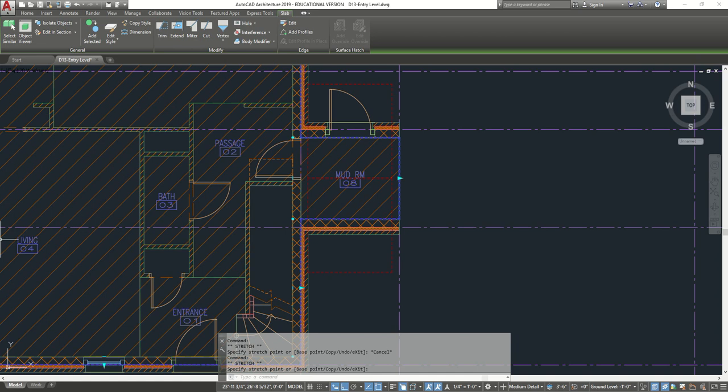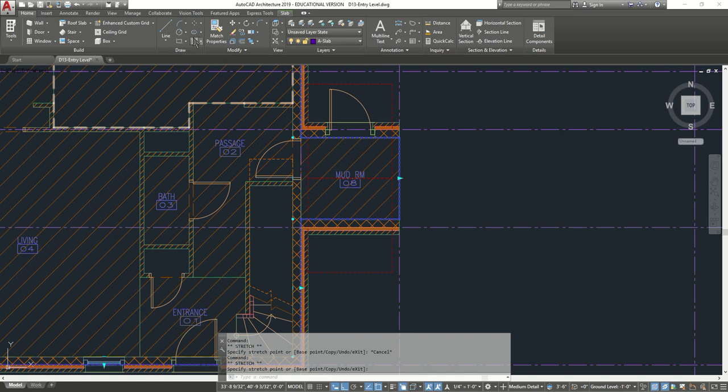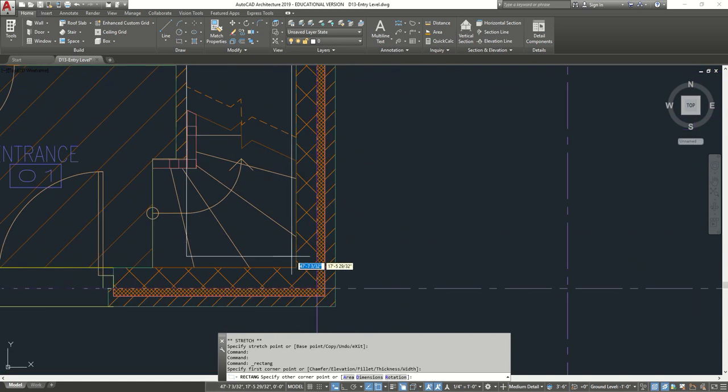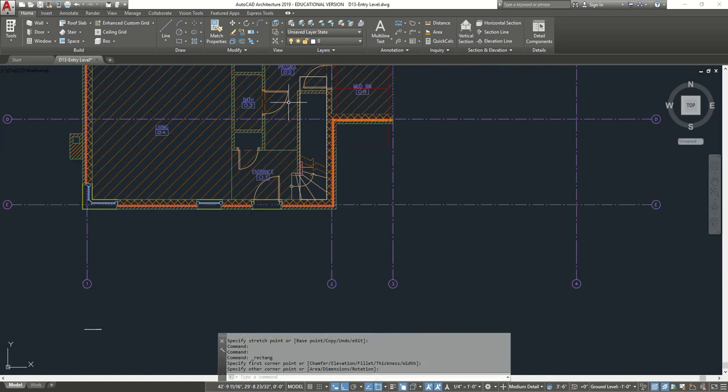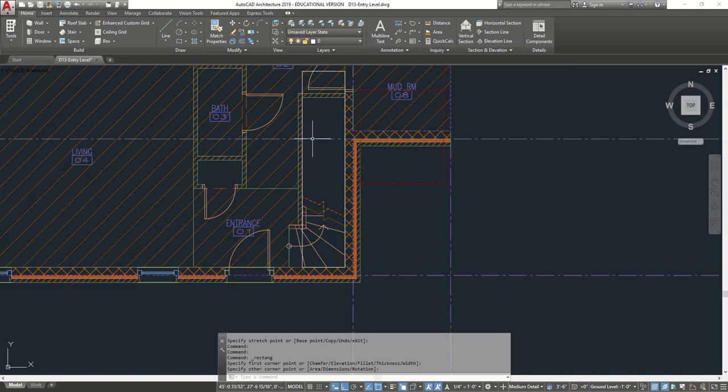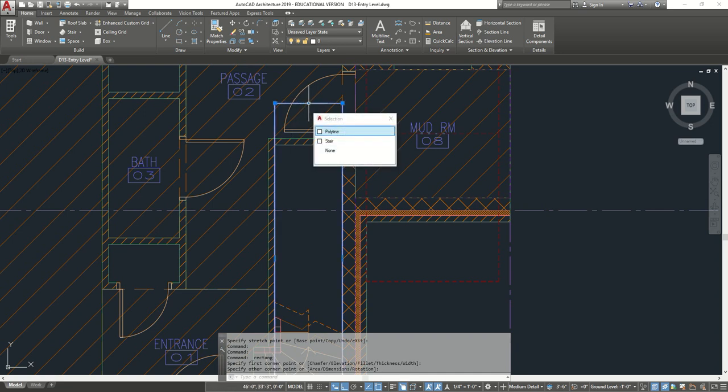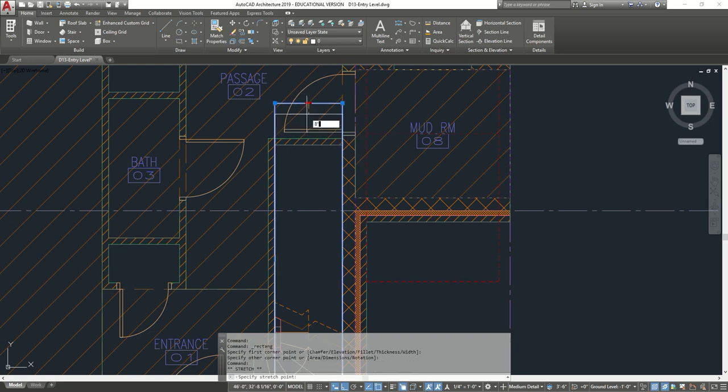Now we're going to draw a rectangle over our staircase. From here, we're going to draw it all the way down to here. We added a slope here before. Now we're going to cut out the hole on top. Before we cut it out, we're also going to lower our rectangle by grabbing here and bringing it down 8 inches. Like so.